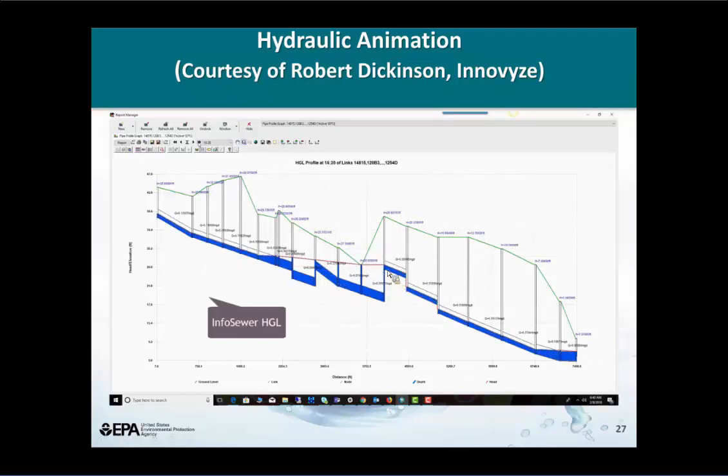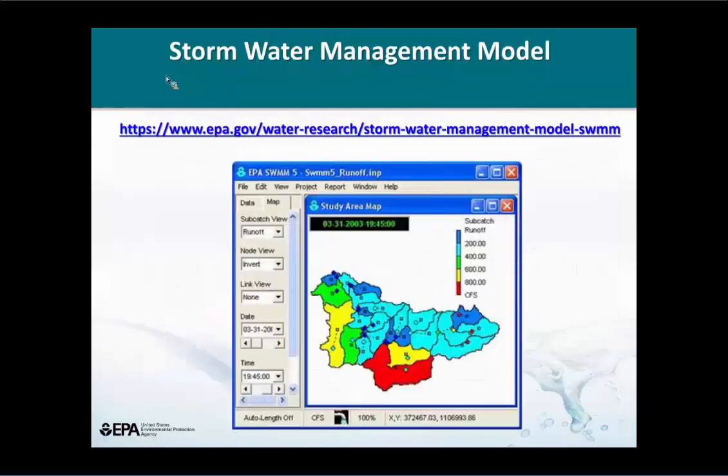And in fact, if this were the outfall and you didn't want to see any flow in here, you'd be able to adjust your hydraulic design so that you could prevent combined sewer runoff. So that is a commercial SWMM. SWMM itself will do that animation, but it's much more elaborate in InfoSWMM and XP SWMM and PC SWMM.